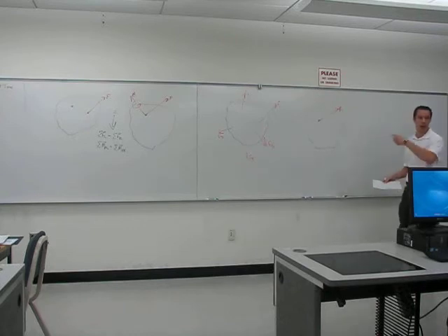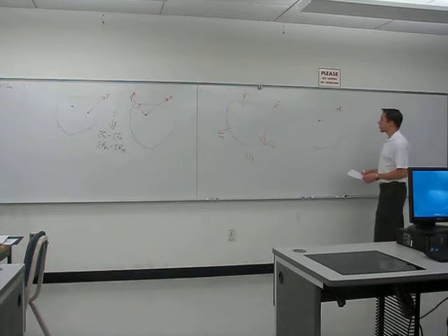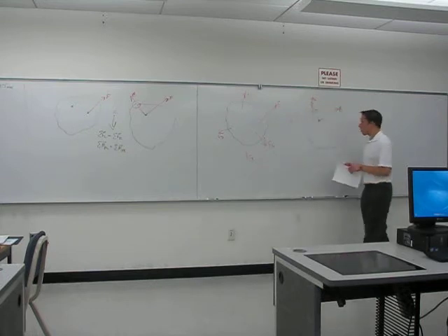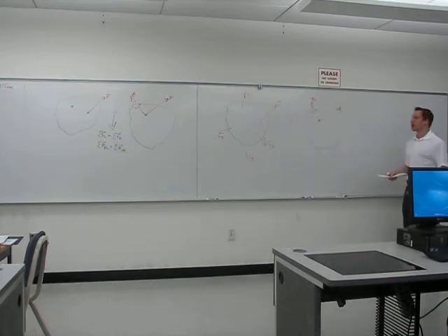That would be the sum of the five individual forces. And then I'm going to have some moment resultant that would be the sum of the 5 moment vectors that have to get added into the picture when we move each of the 5 forces.